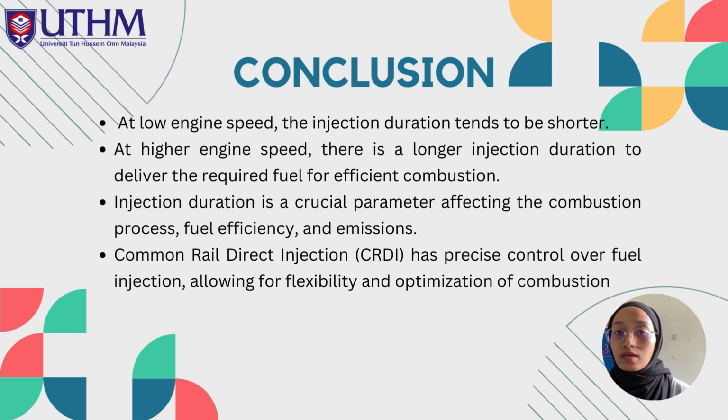Throughout this project, we can conclude that at low engine speed, the injection duration tends to be shorter, while at higher engine speed, there is a longer injection duration to deliver the required fuel for efficient combustion. The injection duration is a crucial parameter affecting the combustion process, fuel efficiency and emissions in a diesel engine. And the injection duration is calculated to achieve efficient combustion and power generation while minimizing emissions.